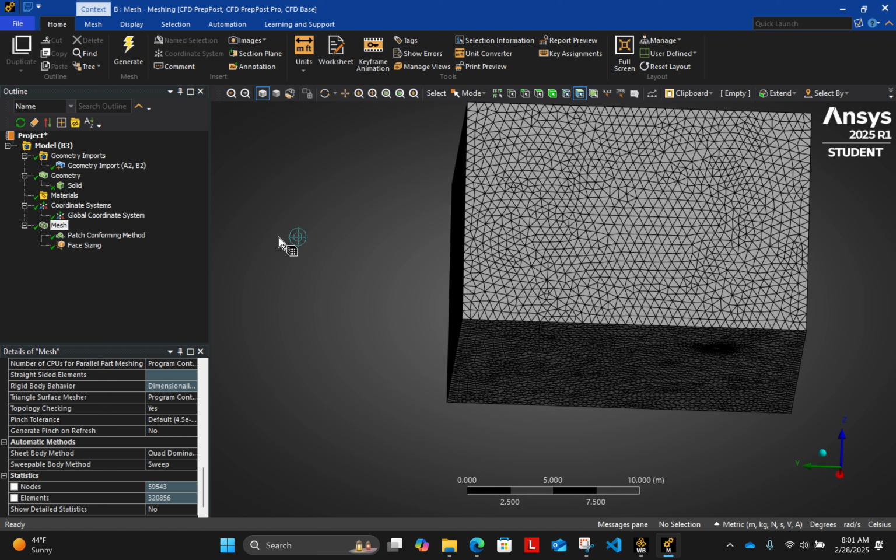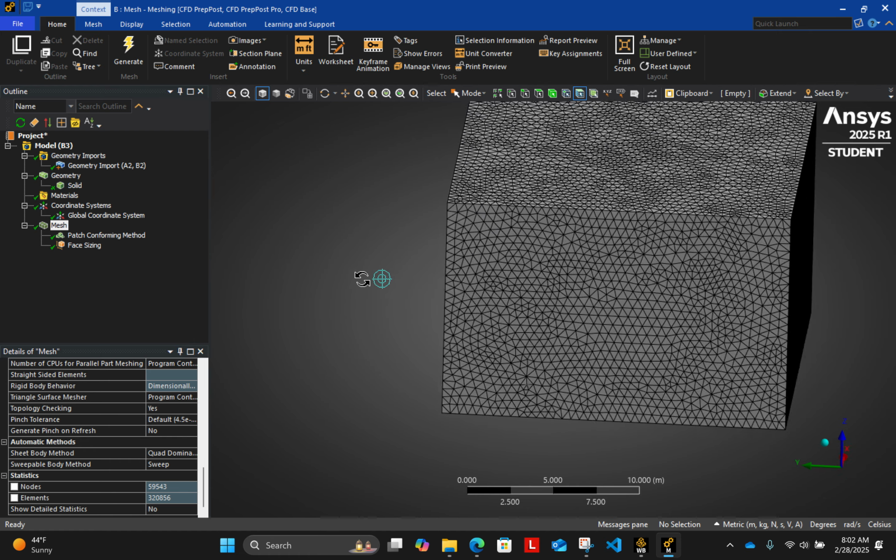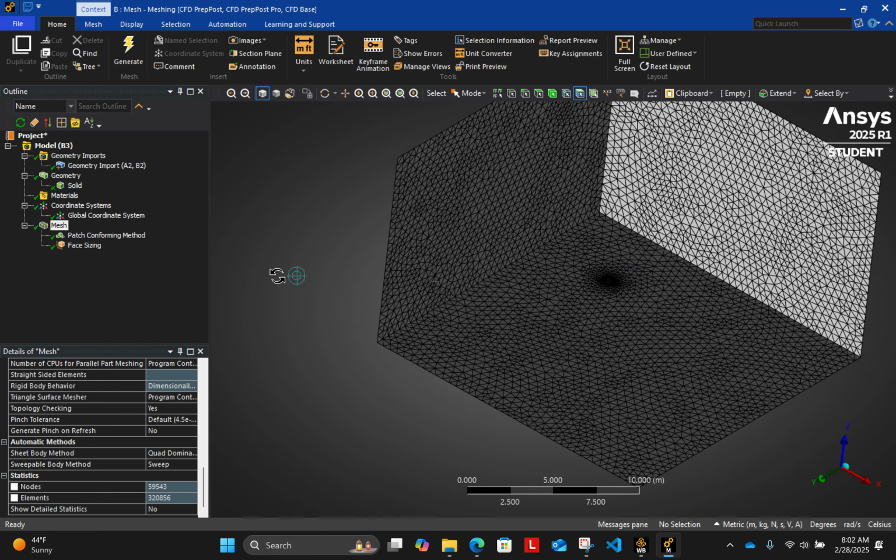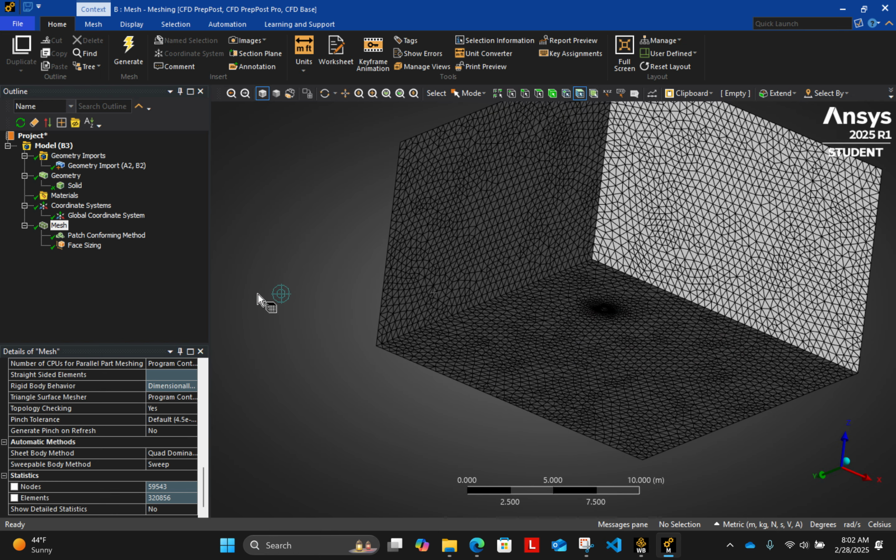The only other thing that needs to be done is to name all of the faces. Essentially, we are creating the boundary conditions. If you recall from your partial differential equations course, to solve partial differential equations, we need to have boundary conditions. These faces, or these boundaries that we are going to name, are going to act as those boundary conditions that we need to solve our problem.